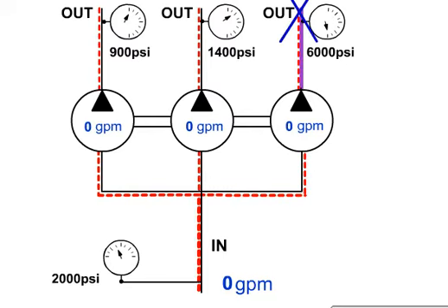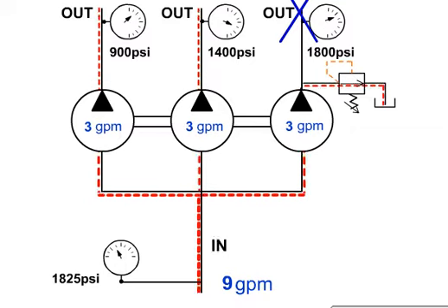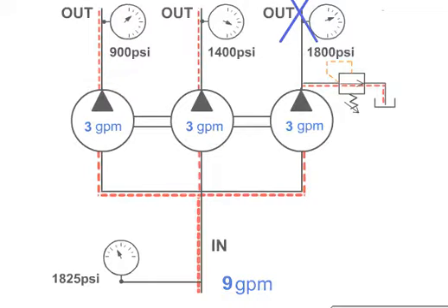If one of the output flows becomes blocked, all of the output flows will be blocked. Pressure intensifies in the circuit that is initially blocked. A relief valve placed in the circuits downstream of a proportional flow divider will prevent pressure intensification. The relief valve will also keep the flow divider from blocking flow to other circuits.